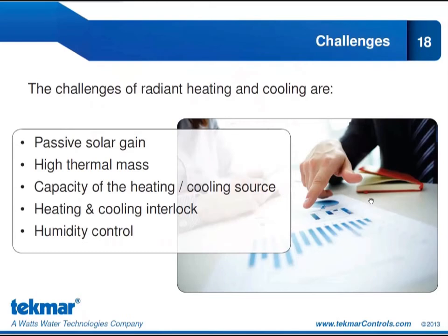And lastly, the challenge that we hear a lot of the time is, well, what about humidity? And that's a very valid concern because radiant systems cannot address humidity. So we need to design the heating and cooling system with humidity control in mind.